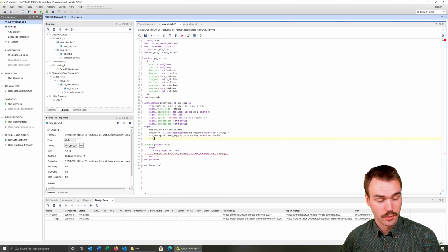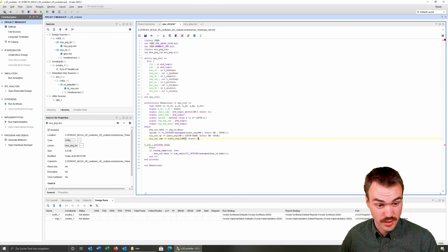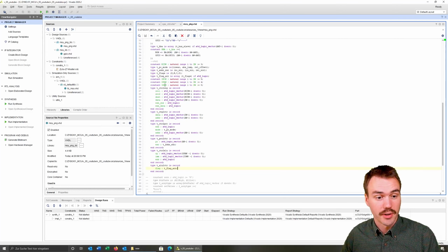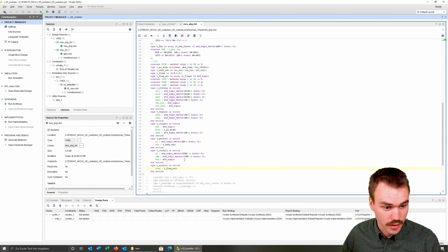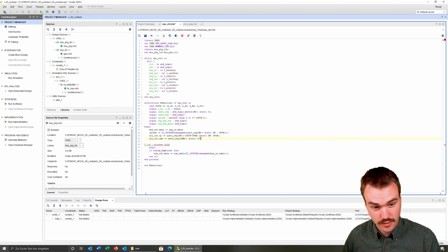Yeah, and the ALU out dot immediate is equal to instruction register, and let's define here a new constant, input output word width -1 down to 0, and we saw that the immediate has a width of 8. So let's define this constant in the MCU package. We already defined it here. Yeah, that's perfectly fine. So yeah, that already works.